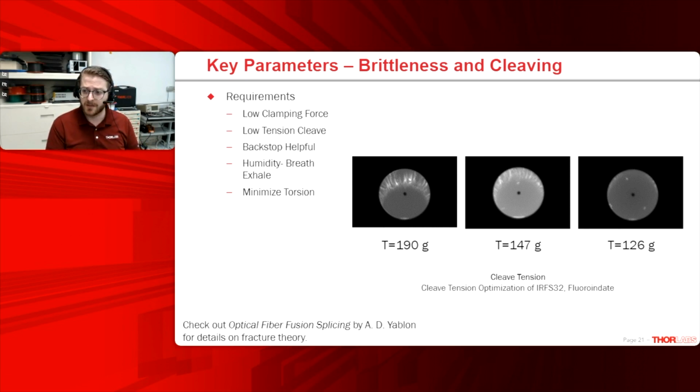Typically, for silica fibers, you'll reduce the tension if you have a structured fiber like a photonic crystal fiber or PM fiber. And so backstop cleavers are already available, but the same is true for soft glasses. You'll often want to use a backstop in much lower tension.